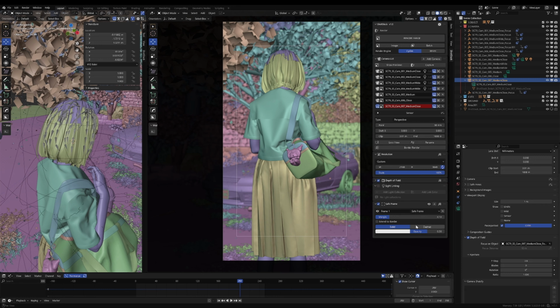First, there's this distance here. We can adjust the distance from the border to the safe frame. And you can also enable it so it becomes an extended safe frame. We can also choose freely between solid or even dashed lines and change its color or adjust the opacity. All these functions can be easily modified and adjusted within this safe frame. I think it's incredibly helpful and convenient. This not only saves you from having to learn unnecessary extra things, but also gives you better customization options. You can accomplish all of these tasks with incredible convenience, right from this highly intuitive and user-friendly menu.